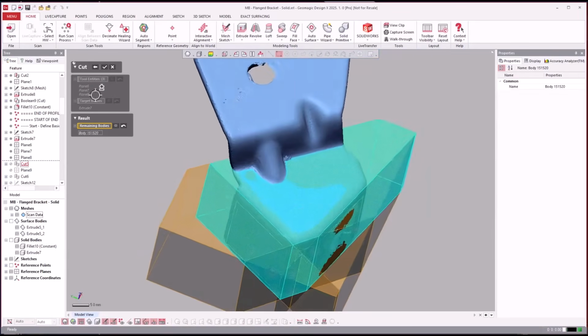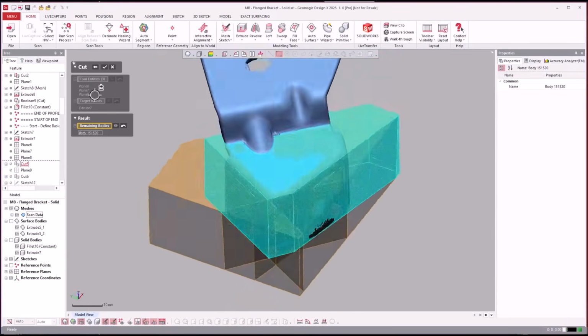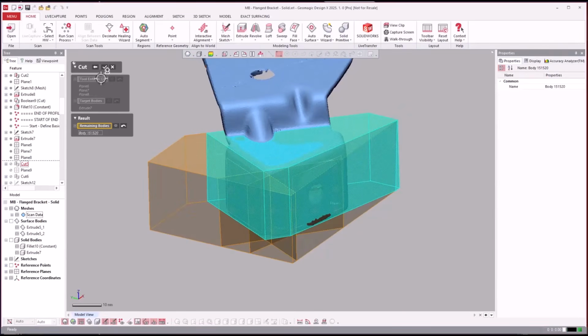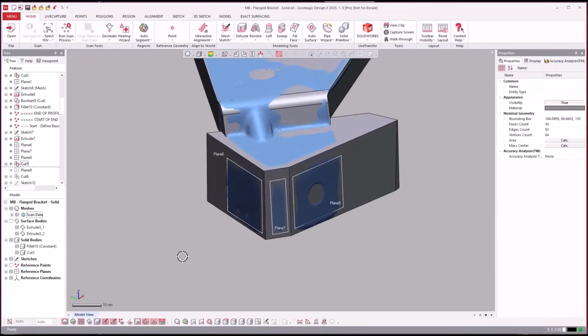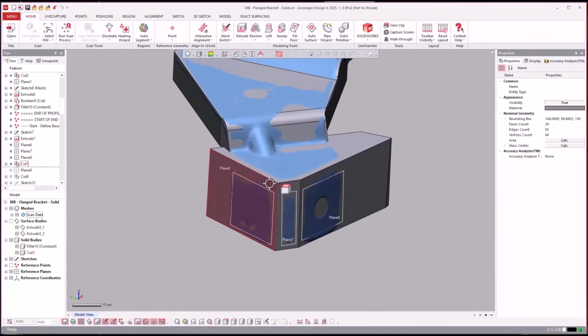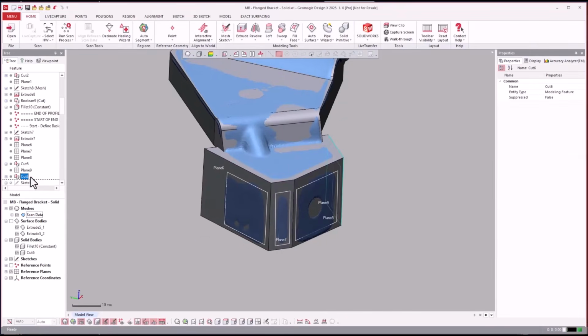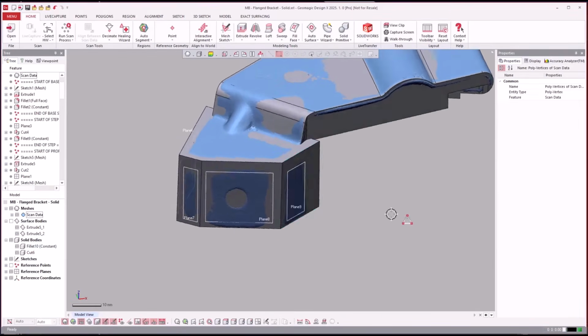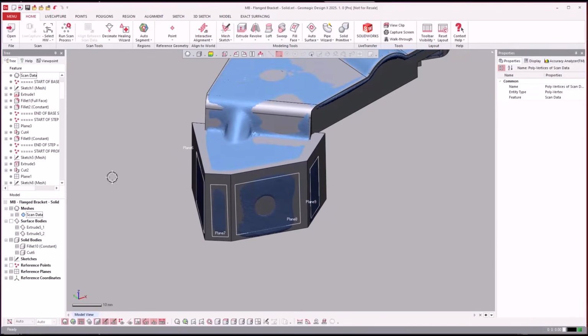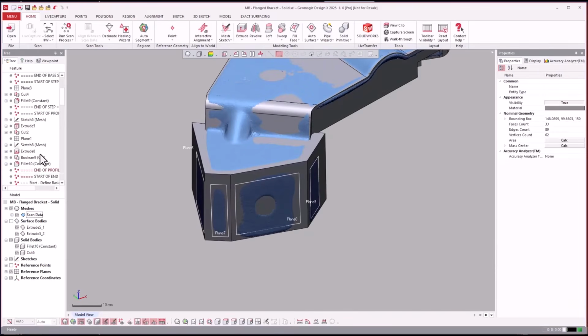We used all 3 of those planes, and we cut that solid with all 3 of those, and then left the remaining body there. There we go. So again, we just used reference planes to cut that. Now we will jump over, and we used another reference plane on that side. We actually could have just done a quadruple cut, add this one to that, just go back in and change it.